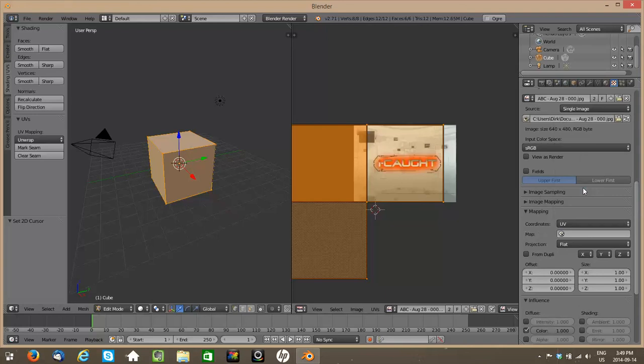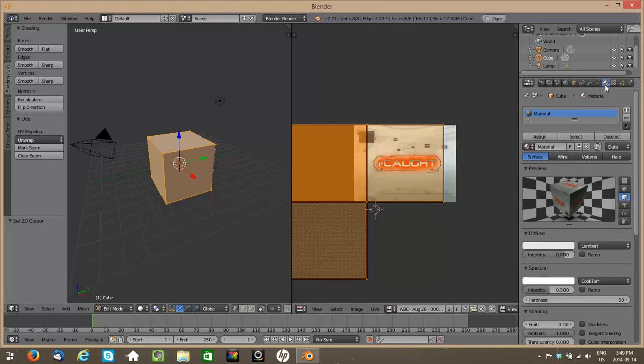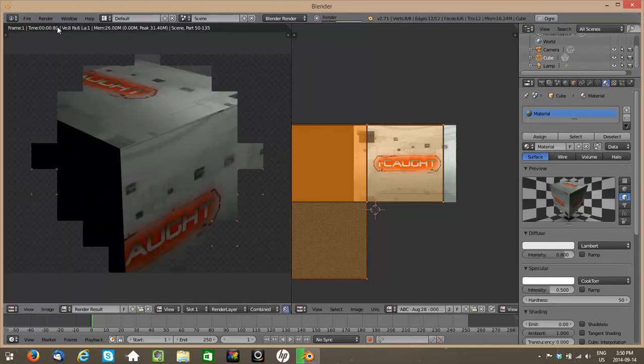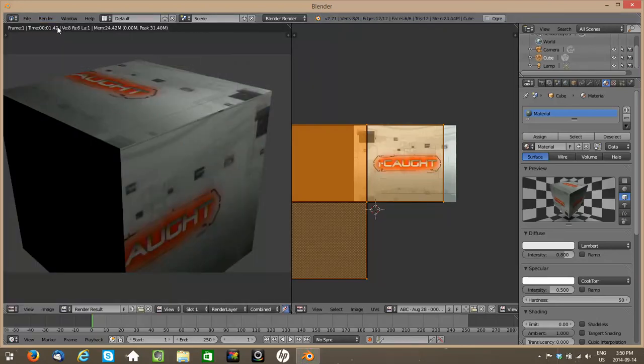Right, so now I've changed again, the view changes, but now if I go back to the materials preview, I see that the magical image that I've chosen has been mapped to at least 3 faces of that cube. And so now I'm closer to being successful than I was before because I've actually gotten the Blender toolbar to use the UV map that I've created here and to apply it actually to the texture image that I've chosen. So let's do a simple render of this and see what I've got. And the thing is, render image, we're going to see in a couple of seconds. Sure enough, the image has been mapped multiple times onto the cube, which is what I want.